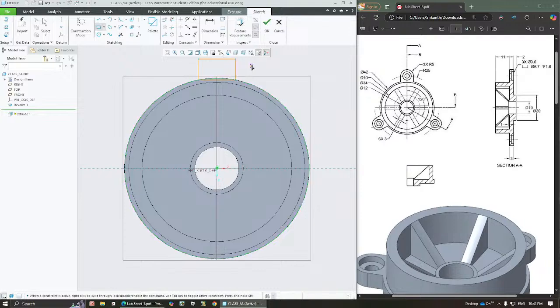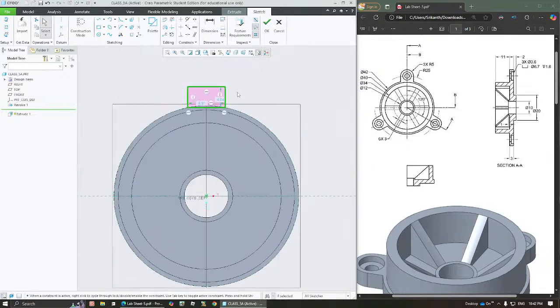Fine. Now, middle mouse button to come out of this command, and when you see this closely, when you drag any one of the edges, you can see it is moving symmetrically, because this point is on this arc and this point is on this arc. Fine. So that ensures that it moves symmetrically. Now just move it up a little, and then take a circle midpoint like this, come out of this and trim it out.